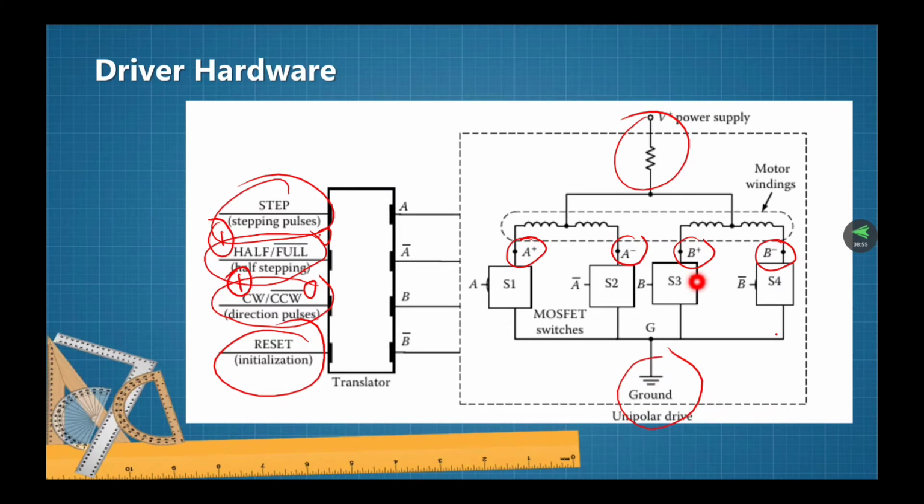If the motor is unifilar for a 2-phase stepper, there should be 3 leads: a ground wire and 2 power leads for the 2 phases. A bipolar drive will be necessary in order to change the direction of the current in the winding.